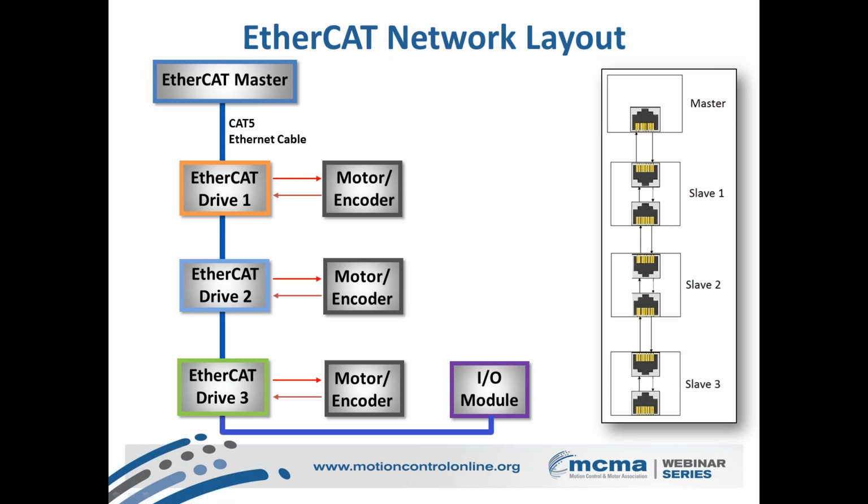And so, an EtherCAT network layout as opposed to the Ethernet. You can see you still have standard Cat5 Ethernet cable between them. The drives are daisy-chained. Each EtherCAT drive will come with 2 RJ45 jacks that act as EtherCAT switches, essentially. It's important to note that although Cat5 cabling and network interface cards are compatible with EtherCAT, standard Ethernet hubs and switches are not. That comes down to the fact that there are no specific addresses in an EtherCAT packet, and routers and switches specifically look at addresses to figure out where to route that information. If it doesn't see one, the system doesn't do well with that.